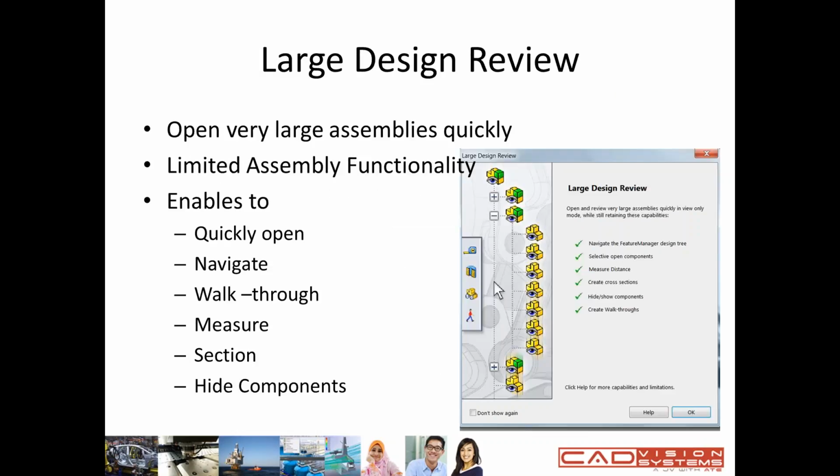So now we come to Large Design Review. Large Design Review basically gives you a quicker way to open an assembly. It enables you to open a very large assembly very quickly, while also retaining capabilities that are useful when conducting a design review of the assembly.